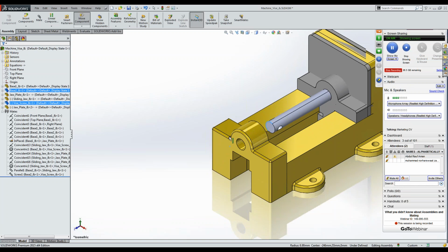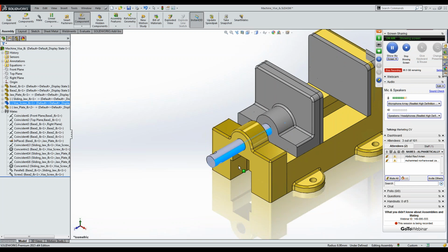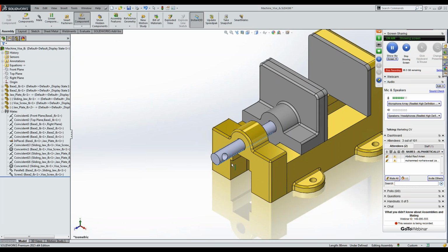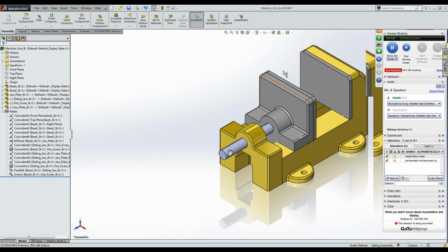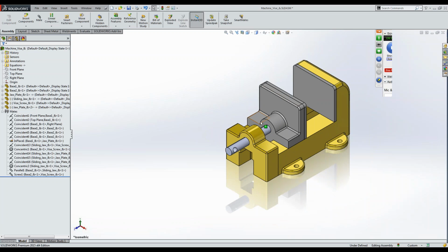But same thing, in the CAD model, SolidWorks will just go over. To really prevent it from going over to other components, the only thing you can do is use motion analysis. Okay, so basically this is the screw mate.